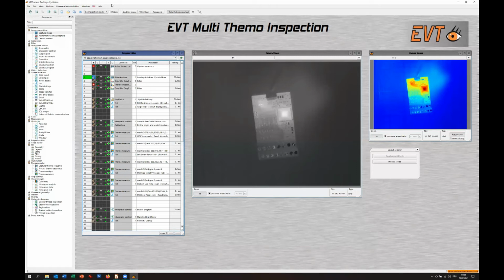And with the next two, it's controlled whether you do the image capture triggered or with a flash or both, especially if you have everything connected to a machine and the part is moving. So you only want to capture images, even for adjusting, if a part is under the camera.